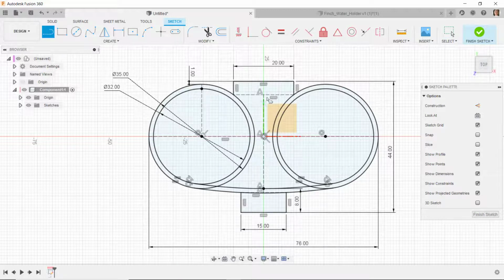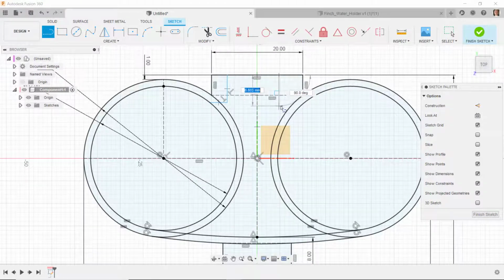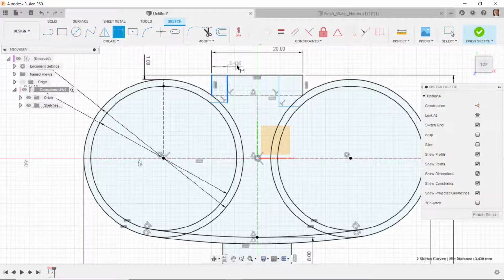So I'm going to create a line coming from here. I'll come down here someplace, and then I'm going to come over to this inside arc, and I'll do the same thing on the other side. So I'll come down over to about here, and I'll come over to that inside arc. Now I want this distance from here to here. I can measure that real easy with the calipers. So I measure that distance with the calipers and I get 2.5 millimeters.